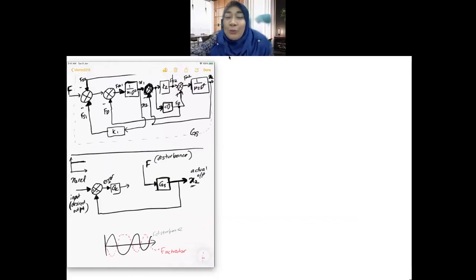Okay, so I can put an actuator after my controller here, to move according to my controller's value. From the controller I can give some value. For example, if you read a journal about MR damper, some expensive cars utilize MR damper or force damper, so they can put another damper in your system here and call that GA. GA is a transfer function, and we call it the actuator.